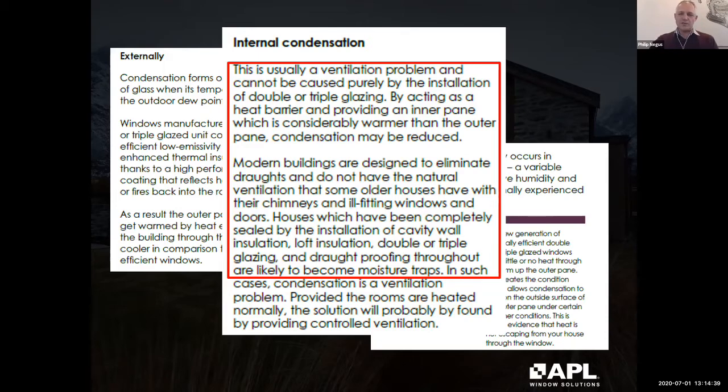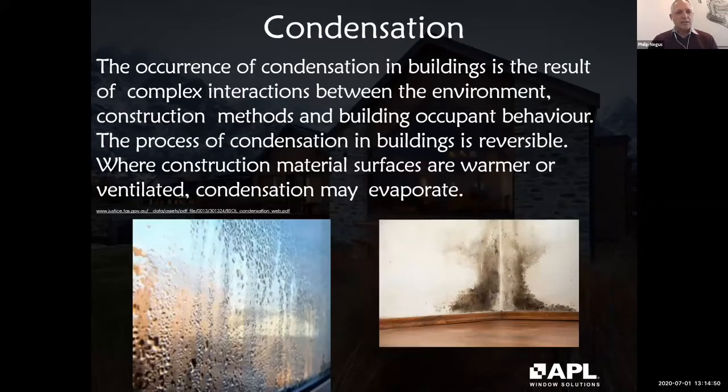But it does mean that the building is wrapped up really tight, becomes airtight as well, and traps all the moisture in there. So condensation, we've heard some horror stories about that. In fact, one of our fabricators used to do a lot of work for Housing New Zealand. I think I remember in one situation where they built a social housing development. They specified the windows as double glazed with double tongue sash handles, restrictor stays, and sash vent. So giving the occupants every opportunity to get some ventilation through the property without having to have the windows necessarily open. So being able to provide some ventilation in a secure way.